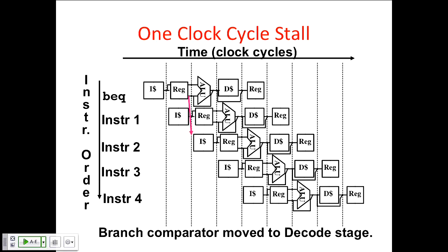Well, the other nice thing about the way this pipeline was designed and the instruction set was designed, I don't actually update any state till I get to the end. Or at least I get to the memory stage. So provided I can find out before these guys write to memory or the register file, I can just blow them away and nothing will have happened. So we design the instruction set so all the updates happen at the end of the pipeline. And so there's kind of no permanent change made until you get there.